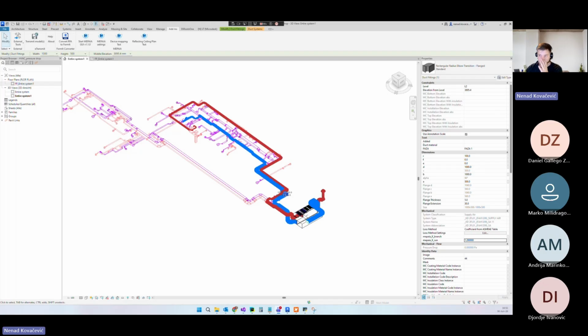But until then, we will need to read the airflow from Revit, and I know that when you're using phases on the same duct network, it can be an issue with airflow. And without airflow, you cannot run the calculation because we do not know the velocity. There is not sufficient input to start the calculation.